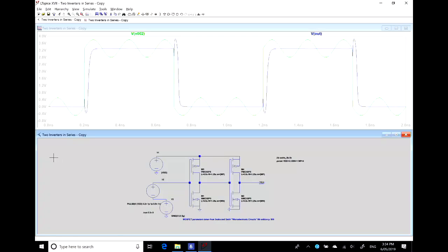Of course, there are these delays and there are these funny transitions. I did say digital circuitry is very noisy. But after that delay, and remember I did say so many times in the lecture that we've got contamination delay and propagation delay, and in between the two we have no idea what the signal is actually doing. Well, in between the two, that's when you get all this mess. But who cares what's happening in there? We look outside of that and we've got a very beautiful 1 here and a very beautiful 0 there.